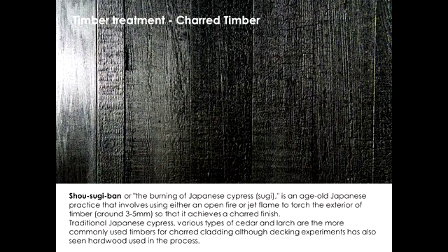But it's really just about burning a Japanese cypress, so a few millimeters of the surface is torched to make sure that there is this charred finish. So it's literally treated, and it's primarily against sunlight and UV rays. Because you probably know that if you leave timber out there and you don't treat it, you don't paint it, it will just change color. It will become that sort of gray after a few years. Not many years, one or two years.